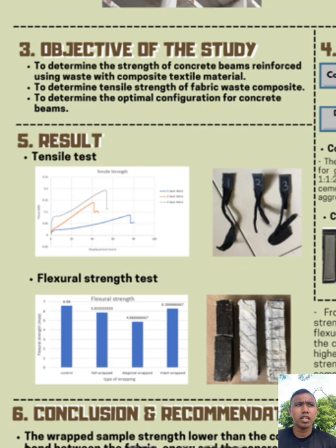So we can see the tensile strength of 3 layers of fabric with epoxy is the highest compared to 1 layer and 2 layers of fabric with epoxy. Then for strengthening the concrete beam, we will use 3 layers of fabric with epoxy to strengthen the concrete beam sample. Then we will proceed with the results of the flexural strength test.